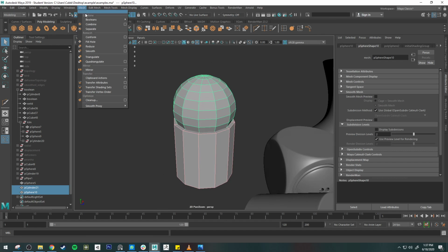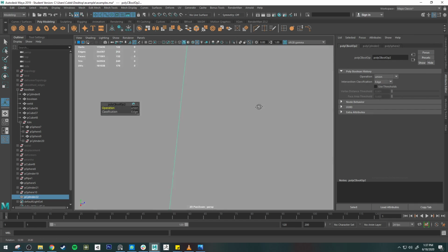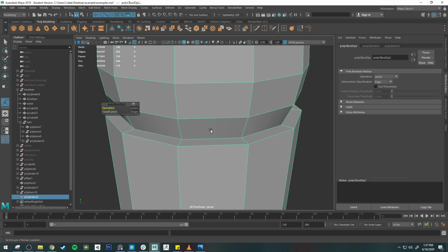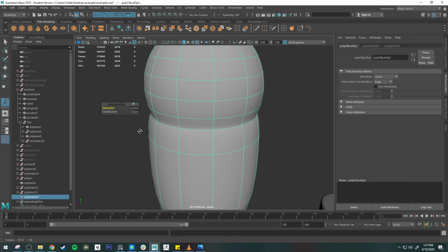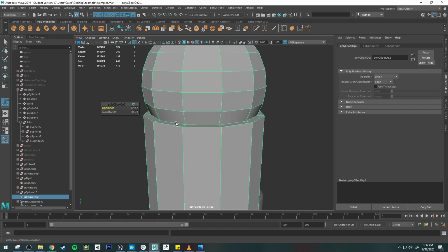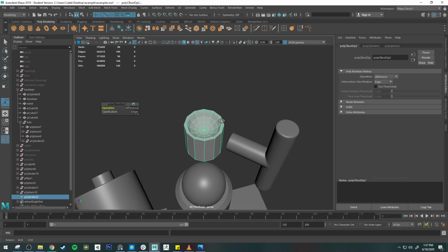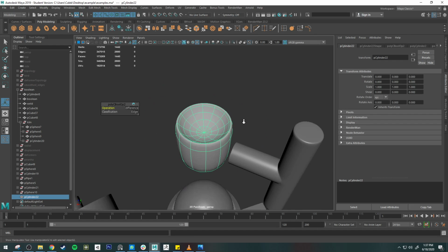And then I just did a mesh Boolean union, right? And it's going to be a pretty darn clean union, right? We might still have edge loops that are separated or not connected, but in this case, since these are lined up almost perfectly, it seemed to do a good job. I can go ahead and let's do a difference instead. If instead I wanted to cut a bowl into that shape, right?